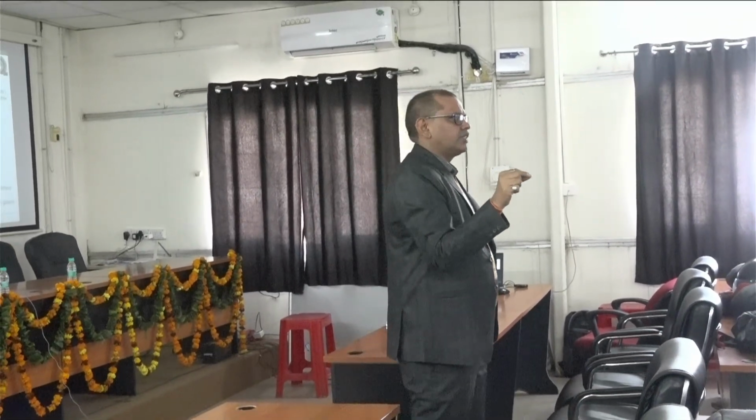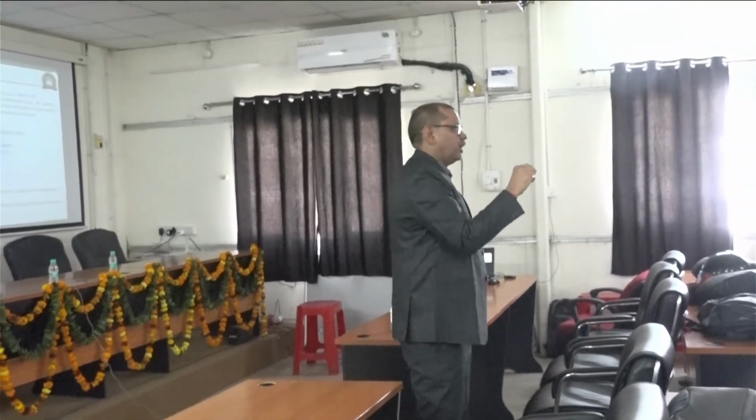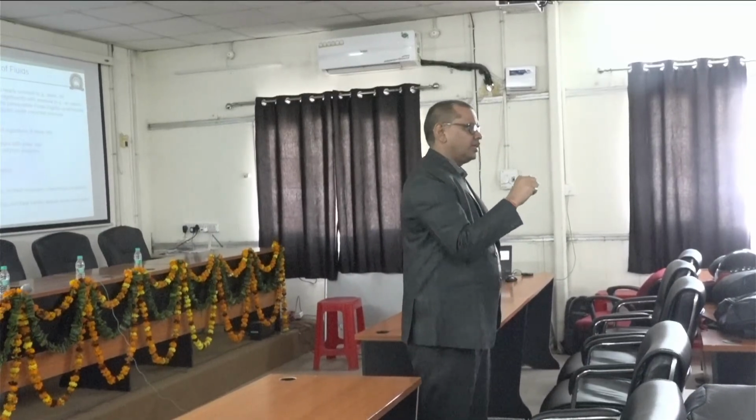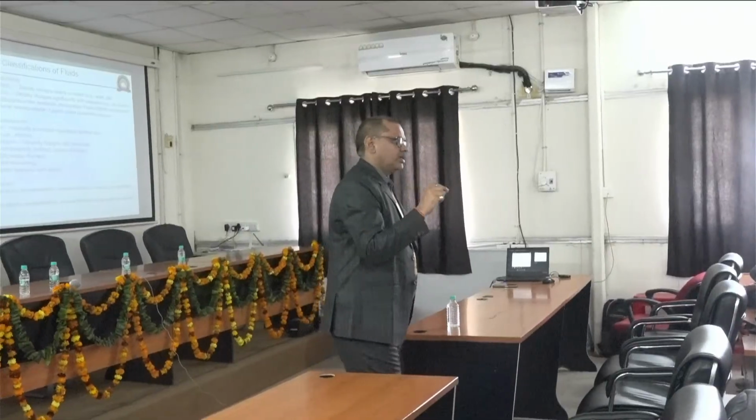So what will be the mathematical expression? The mathematical expression will be tau is equal to mu gamma dot plus some constant value, and that value will represent the plasticity nature of the fluid, that is the yielding stress. So tau is equal to tau 0 plus mu gamma dot will be the linear model for the viscoplastic material. It is just like y is equal to mx plus c, the equation of a straight line. And the same thing you can find for the Bingham plastic model.